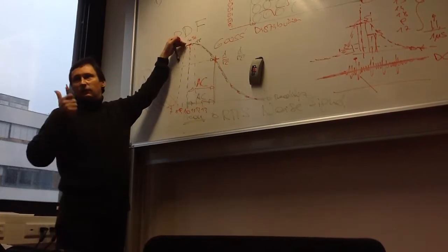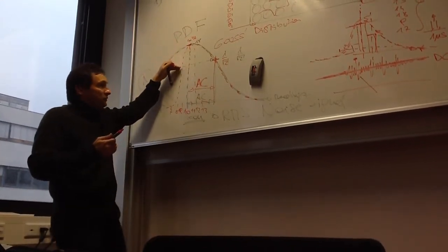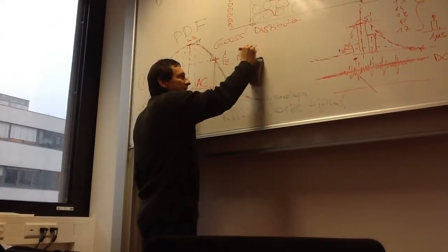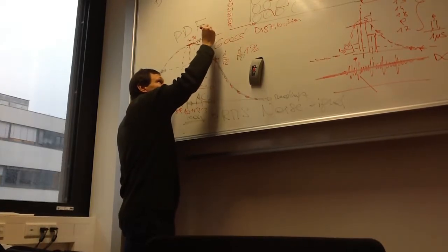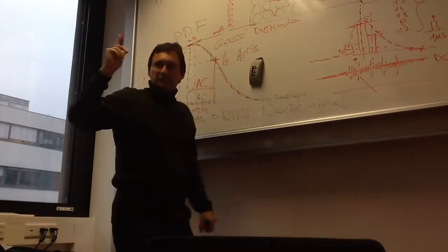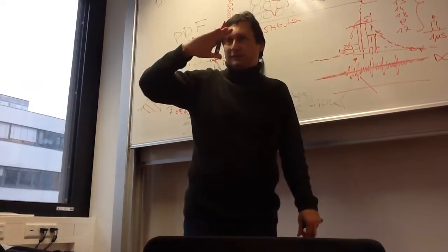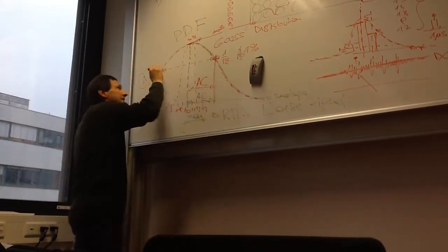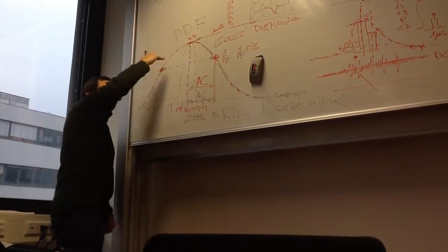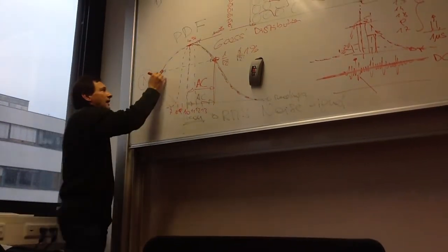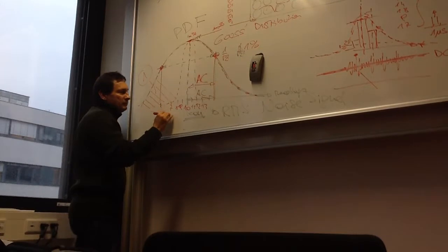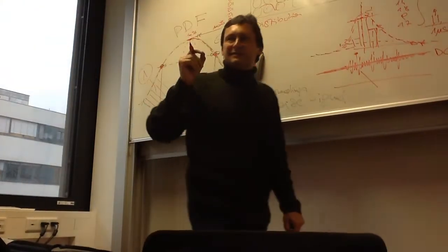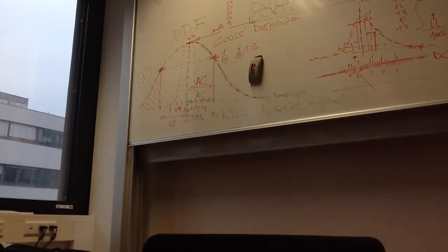So here it's 1, and we go down to the value of 1 over square root of 2. This is 71% of the peak. The peak is 100%, we go down to 71%, draw a horizontal line, and here we are cutting through that distribution, and this value from here to the mean is the standard deviation, and this is defined as the RMS value of the noise signal.